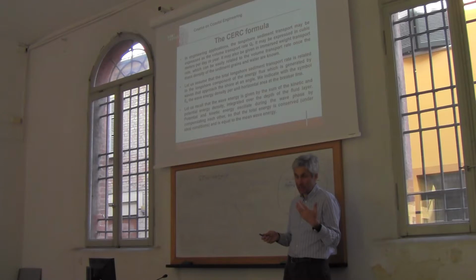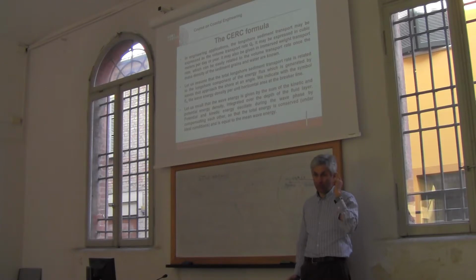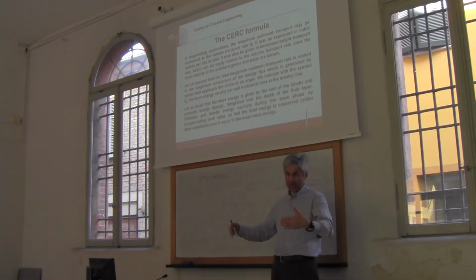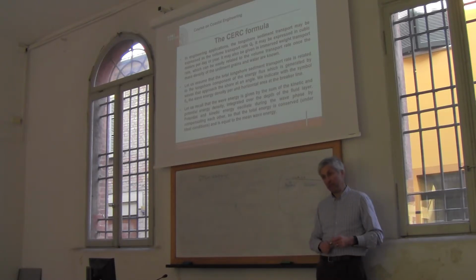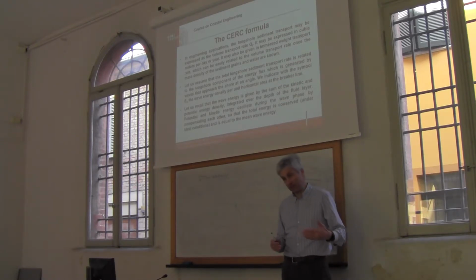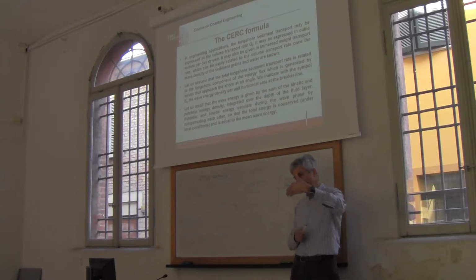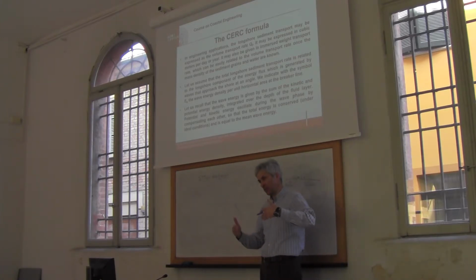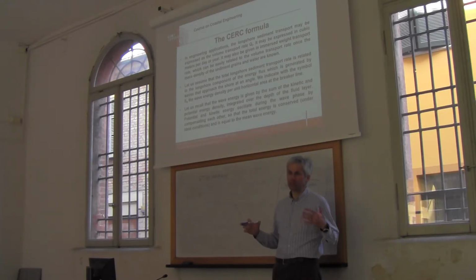The energy flux is easier to describe once you know the wave amplitude, once you know the wave velocity, the group velocity. It's easy to compute the energy flux that is transmitted by waves. If you want to compute from the energy flux the flux of mass, this is very complicated. And therefore, in order to skip this step, the assumption is that we relate the long-shore sediment transport to the energy flux.